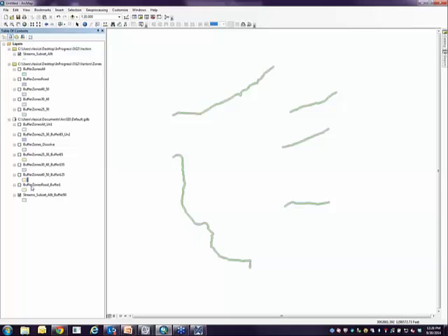If it's 25 to 30, make that buffer 85 feet, etc. And you start to get areas like this where different zones with different slopes have a different width for the buffer. Then I just dissolved all those zones together and saved it out as a shapefile to export back to ENVI.